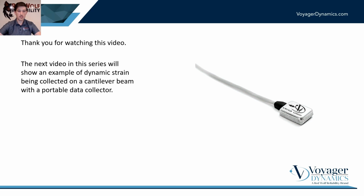The next video in this series is going to show an example of dynamic strain being collected on a cantilever beam using the FDS sensor with a portable data collector. We're going to use that as an example of how you can set up the measurement with the FDS sensor and where to expect the highest strain amplitudes on a cantilever beam, just as a good example of real data being collected.